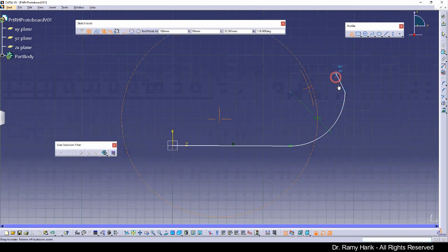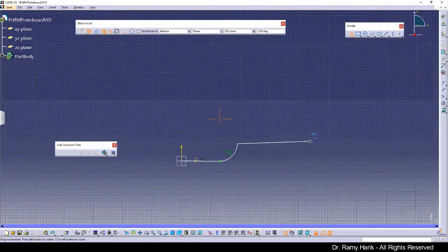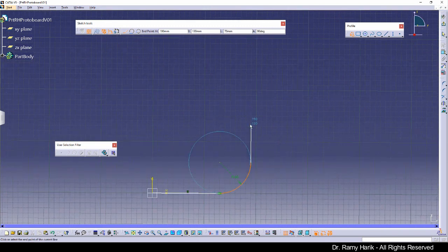Now we're going to go up. I'm going to move my part a little bit here and zoom back in a little. We are going to go up approximately 95. So once again, you can press tab, go to length, and literally put 95. And you want it at a 90-degree angle. So this is, and we can delete some of the dimensions later.